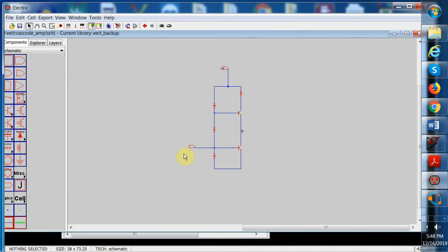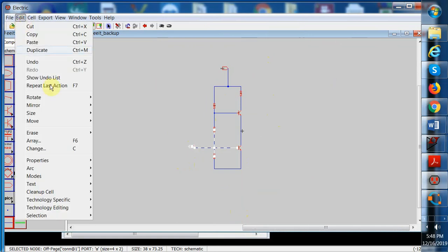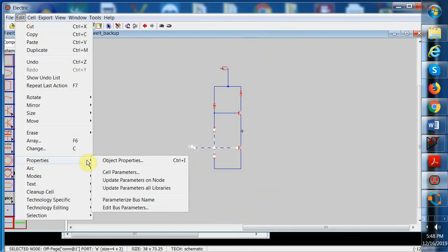As I have already explained in the last lectures, it's very difficult to come up with a large value of capacitance in integrated circuits. So in this case, we connect a so-called input pin here. But for this input pin, the user of this circuit will have to add a discrete capacitor to connect the input voltage into this pin.